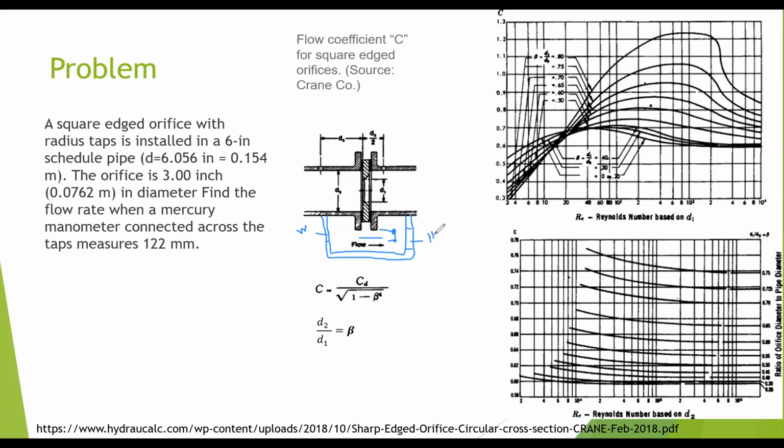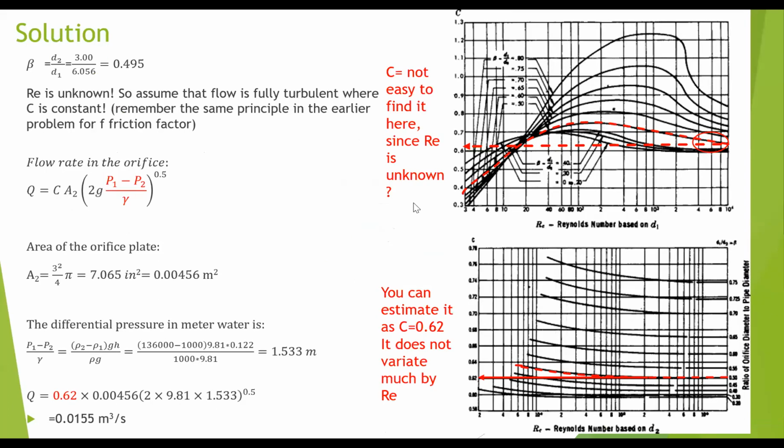Okay, that's why while you are calculating the pressure difference, you should use the equation accordingly based on the manometer theory. And I am pretty sure that you remember everything because it was, again, your final exam question in your fluid mechanics course. And while we are calculating pressure difference, we used here the density of mercury minus water.